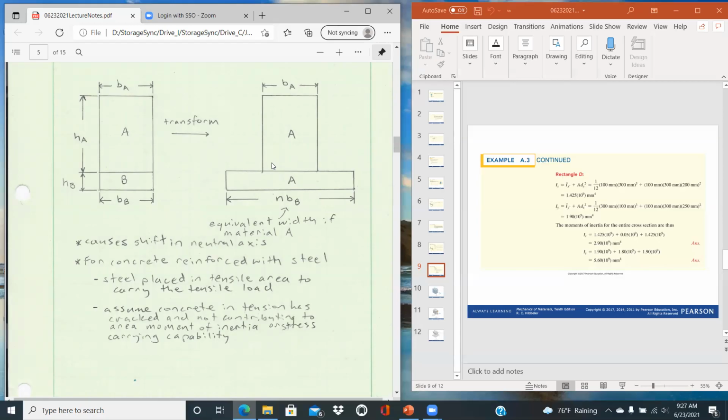And so when you drive by a construction zone, you'll notice that they'll put the steel rebar towards the bottom of the concrete pour. And they do that so that the steel is able to absorb those tensile loadings near the bottom of the structure.